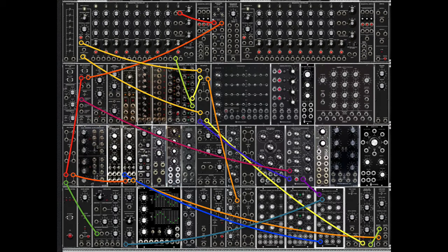When you bring the switch to the middle, it reverses. 5 volts comes out. The inverter takes it down to -5, which is 0. So stage 9 is no longer being called. And +5 makes the sequencer play. Bottom line, switch up, no play, switch in the middle, play. And every time it will start on stage 1.